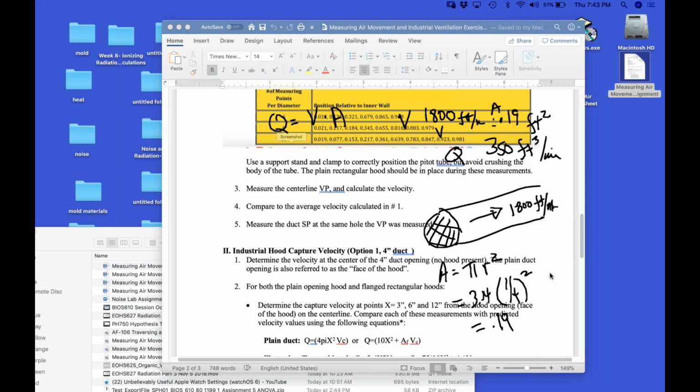Okay, what's the velocity pressure in here? Zero. What happens to the static pressure? It goes higher. Well, you know that energy. So the static pressure is potential energy, right? It's waiting there to do some work. And when you take that off, it becomes kinetic energy. So the static pressure goes down because it's exchanged for velocity pressure. Okay, good.